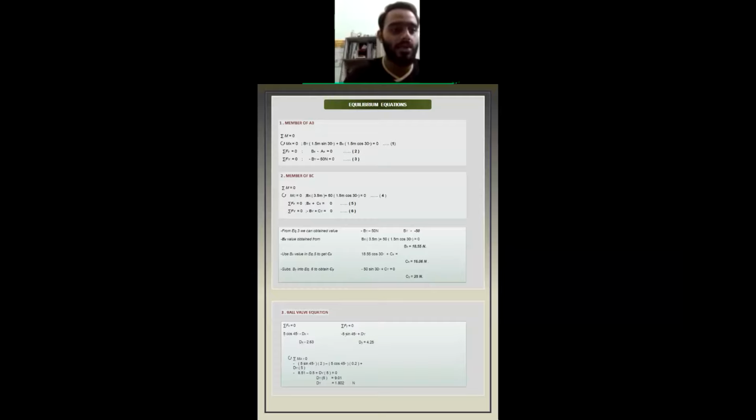Since we have the Bx value, we can use it to solve Cx, which is 18.55 cos 30 plus Cx. We get the Cx value of 16.06. Next, we substitute to get the value of Cy: negative 50 sine 30 plus Cy.